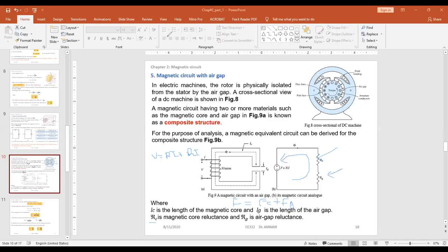Yes. Okay. So there is nothing new here. We have different terms, we defined things like reluctance and density, but the behavior of those physical systems is almost the same. Here we have two different materials, so we have different reluctances. It's the same thing as when we have a circuit with different resistances. And also F of the circuit equals FC plus FG, core plus air gap.